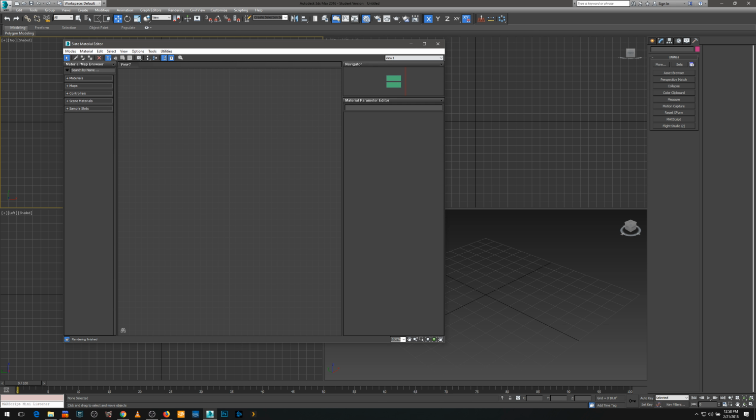And press M or click the icon, and then it will allow us to give the option in the material map browser area. In the blank spot, right click and choose Autodesk Material Library. These are the materials that we're going to use through most of the demonstrations. We'll get into some custom things, but we want to make sure that we have that. It has all the basics that you need, metals, wood, you name it, paint, it's all there. So we can close that for now.